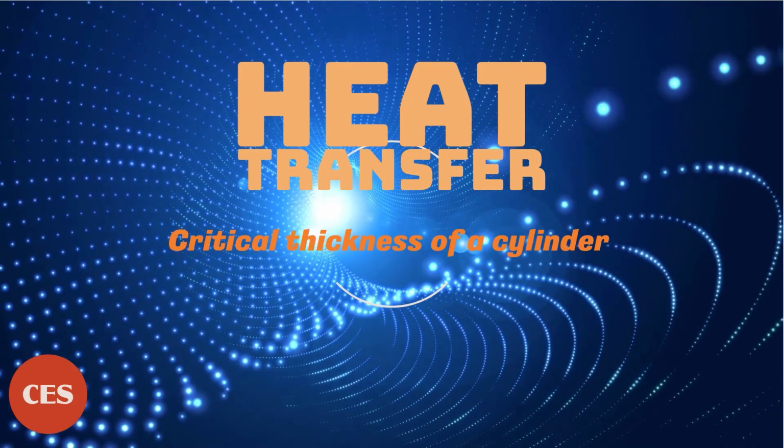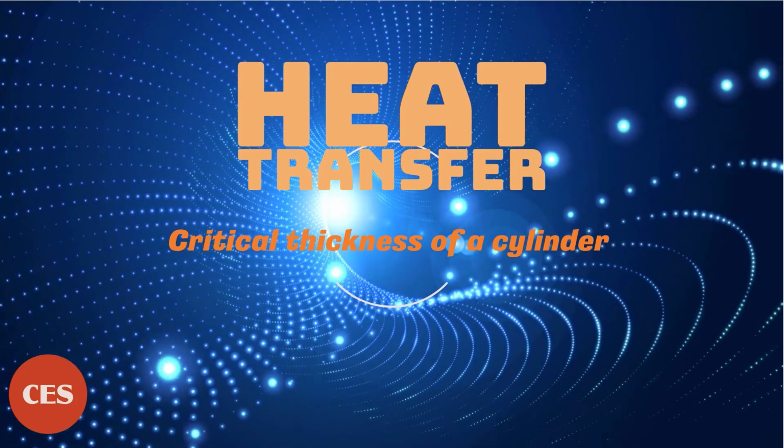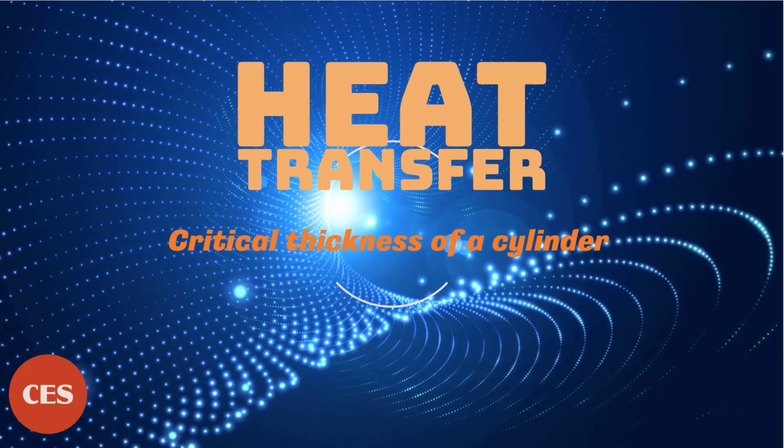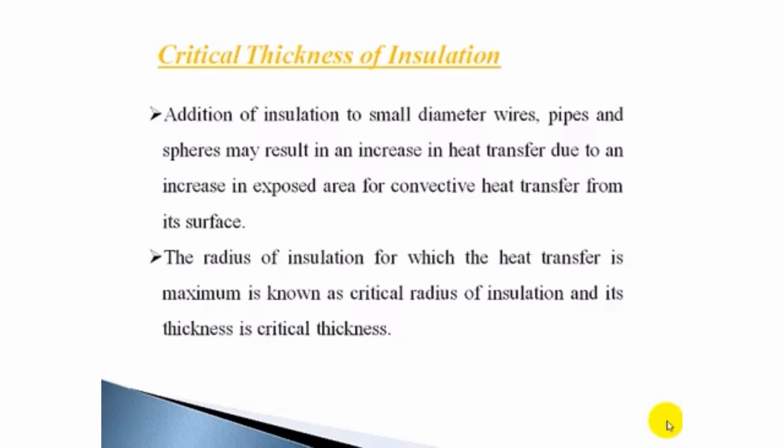Today I am introducing a new topic, critical thickness of insulation. When you hear about thermal insulation, the first thing that comes to your mind is that insulation always reduces the heat transfer, which is a misconception. In case of plane surfaces, addition of a layer will always reduce the heat transfer irrespective of the quality of the insulation material.